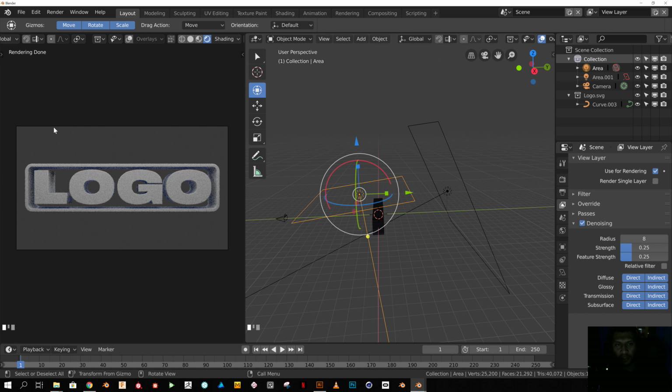But before that I will just select the area that I want to render, since we have a lot of wasted space around here, and since Cycles takes a little bit longer, I would suggest you do this too, so you save some time. So just by hitting Ctrl B or Command B while you're in your camera mode, you can select the area you want to render, just like this. And if you have the overlays activated here, you'll see that you have this red box, and this is the box that will be rendered. The rest will not be regarded.